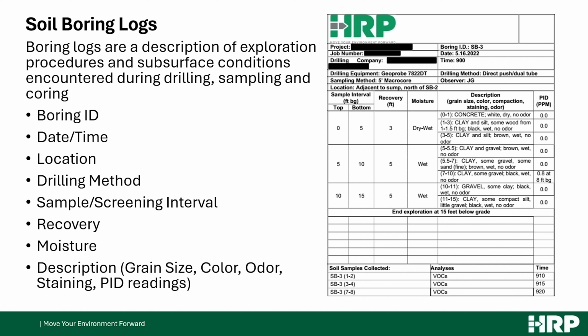The other important information is the depth to water that you see when you install the soil borings. Did you intercept the groundwater table? Did you hit refusal? Do you think refusal is just something that the geoprobe couldn't get through, or is it actually bedrock? These are all really important pieces of information when we get back from the field and we're trying to develop a holistic conceptual site model for contaminant fate and transport.